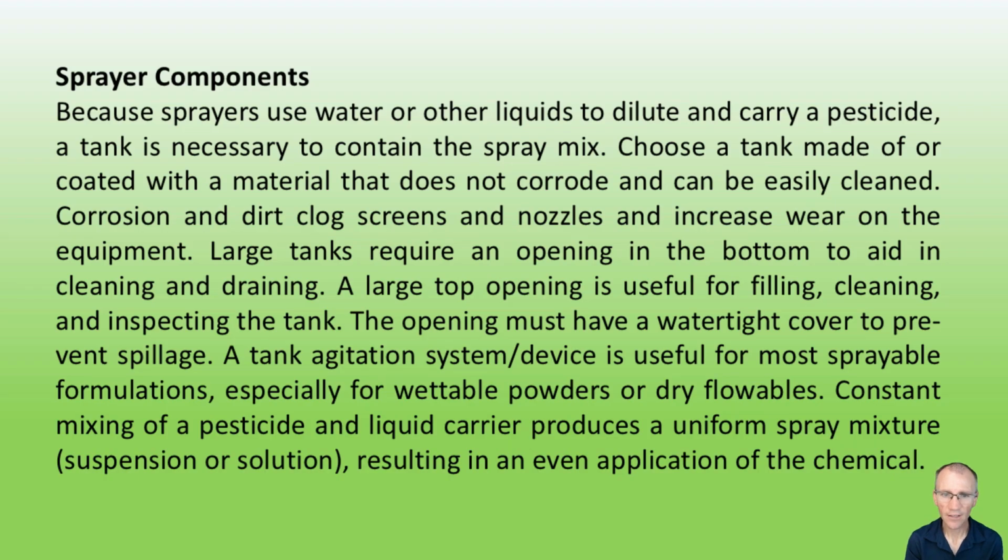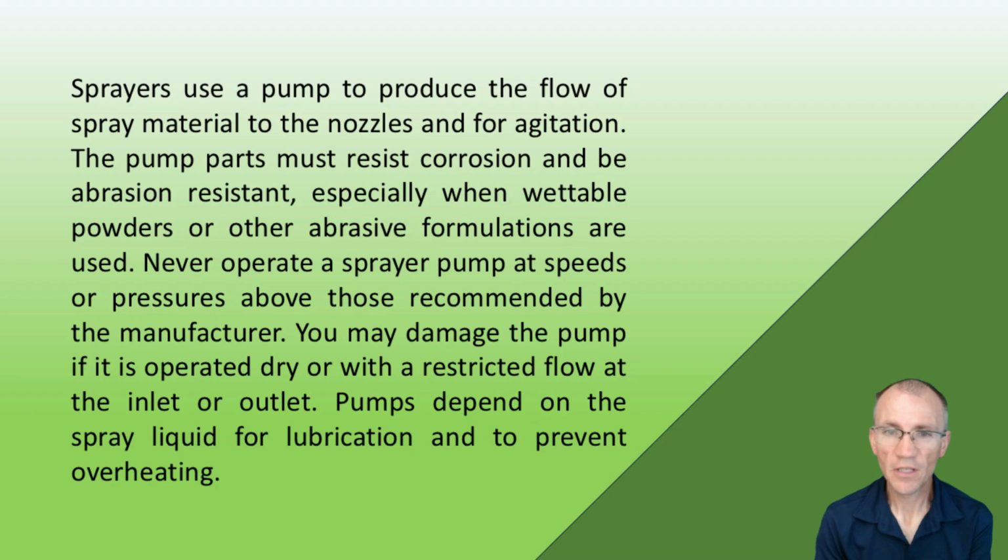A tank agitation system or device is useful for most sprayable formulations, especially for wettable powders or dry flowables. Constant mixing of a pesticide and liquid carrier produces a uniform spray mixture, suspension or solution, resulting in an even application of the chemical. Sprayers use a pump to produce the flow of spray material to the nozzles and for agitation.